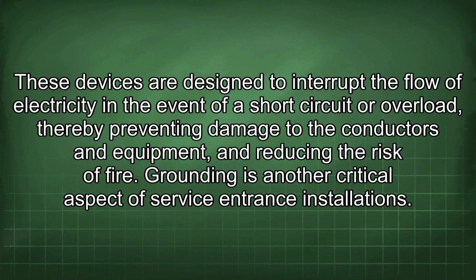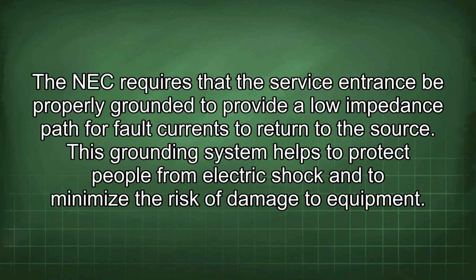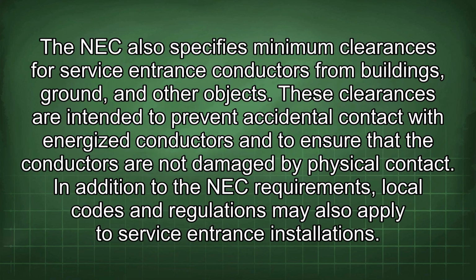Grounding is another critical aspect of service entrance installations. The NEC requires that the service entrance be properly grounded to provide a low impedance path for fault currents to return to the source. This grounding system helps to protect people from electric shock and to minimize the risk of damage to equipment. The NEC also specifies minimum clearances for service entrance conductors from buildings, ground, and other objects.